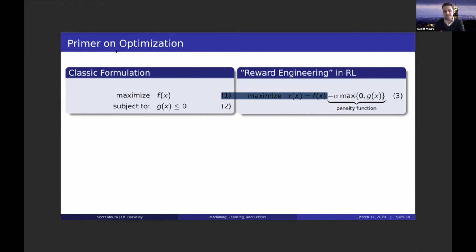Once you try to add more physics into your models, you're going to increase the number of states. And actually, the bigger issue is not the number of states, but the nonlinearities. You mentioned Stephen Boyd, who's really popularized and advanced the science around convex optimization. If your model stays linear in the states, even when it's large, then you can use traditional optimization and it has polynomial time complexity. But when we're adding Butler-Volmer kinetics, we've got diffusivities that are functions of concentrations and temperature. You want to vary porosity across the cell, as Candler Smith described in the design, very cool idea.